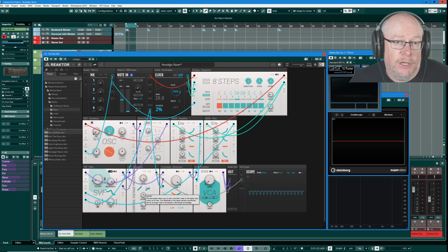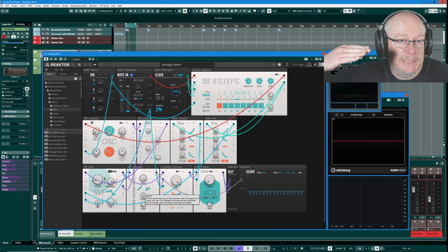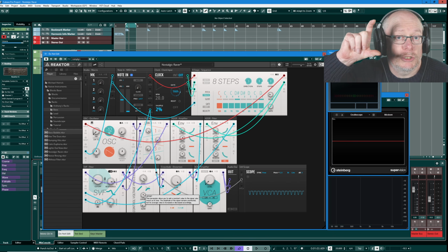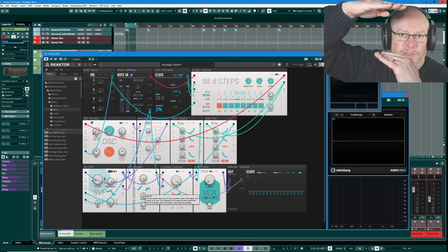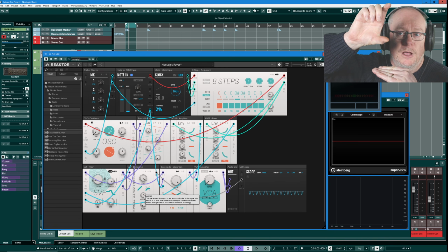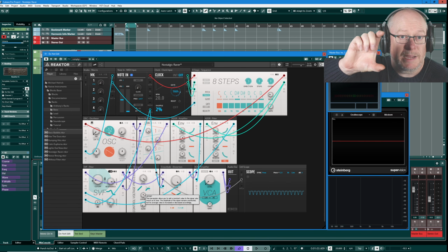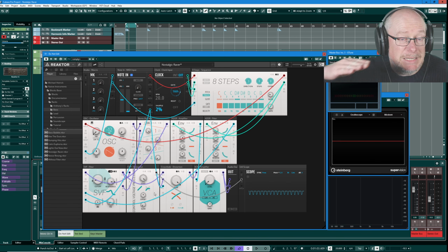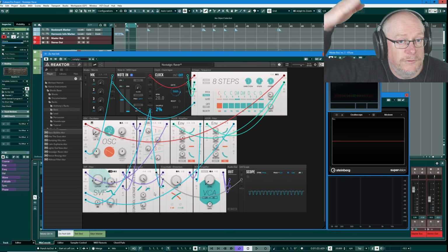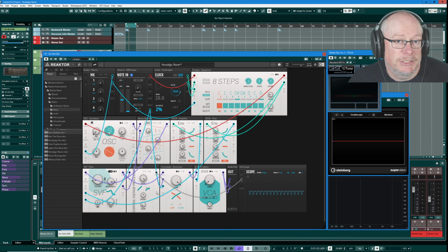What we achieve with the offset knob is that we're able to control how much of the wave is clipped. If we've got a wave that's this big, and half of it is being clipped, if we subtract an amount of control voltage from the entire wave, you mitigate the result of half of your signal being lost. You basically manage to retain more of it. If I get the sequence going again, you'll be able to see this really easily.